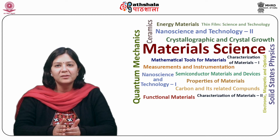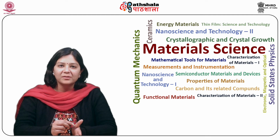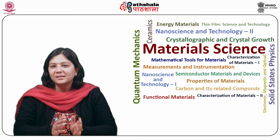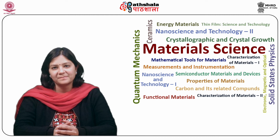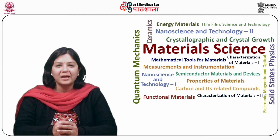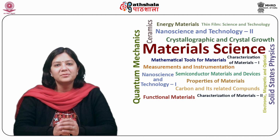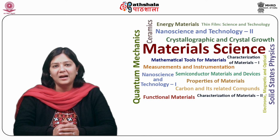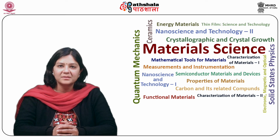Alternatively, maskless lithography can also be used, wherein a precise beam is directly focused onto the wafer without masking it. However, this technique is not a common practice in commercial applications. Exposure systems can be classified with respect to the optics used to transfer the image from the mask to the wafer, and these are contact and proximity systems.